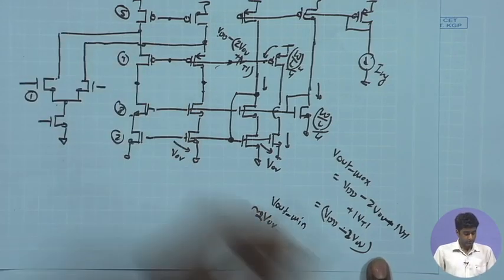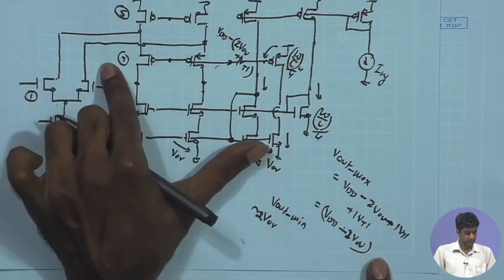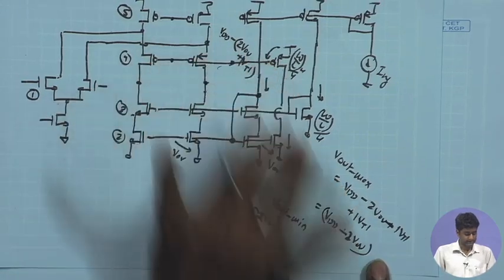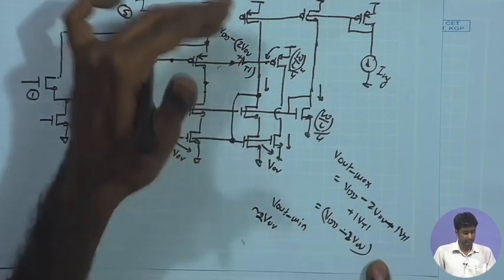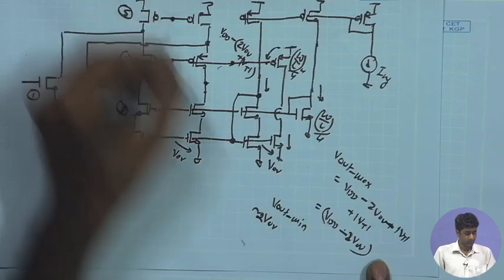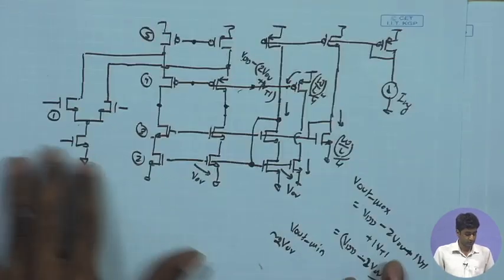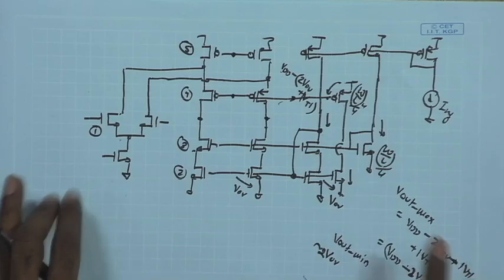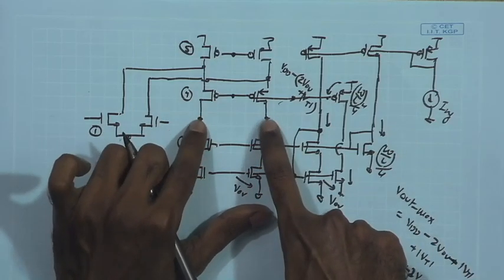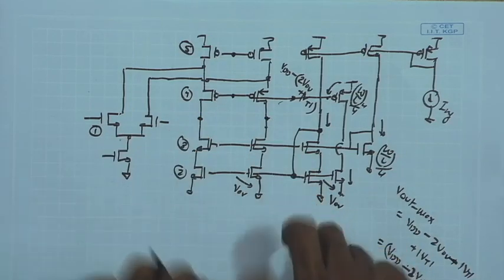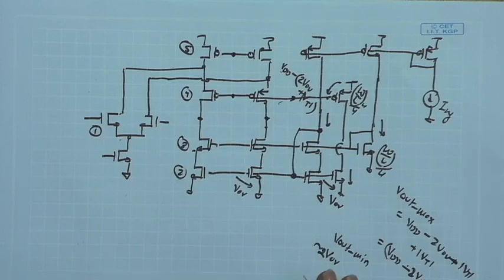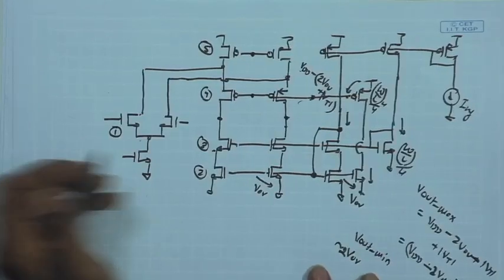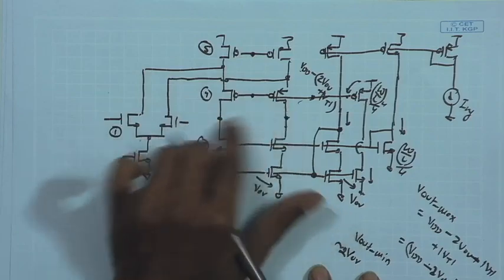So, the gate potential of the 2 PMOS over here for the fourth pair has been set accordingly, so that we get the maximum potential over here, but now we also need to set the gate potential of the topmost PMOS pair, and there we need to have some control, so that we can determine the common mode DC level, and there once again we can take the help of a common mode feedback amplifier, an error amplifier, so that we can set a desired potential over here.